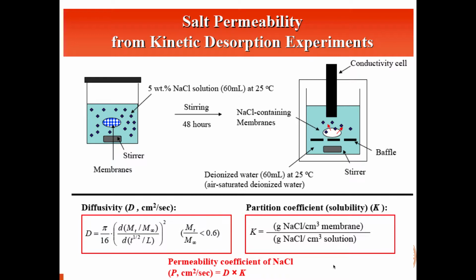If you take it out of that solution and then put it into pure water and stir it so that the solution stays well mixed, over time, some of the salt that was in the sample will come out. And as it comes out into the water, you can detect that in terms of a rise in electrical conductivity of the water. And from that conductivity rise with time, diffusion coefficients can be determined. I'll show you what this means in a moment.